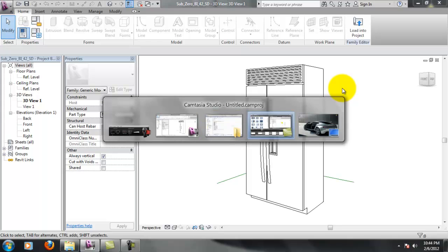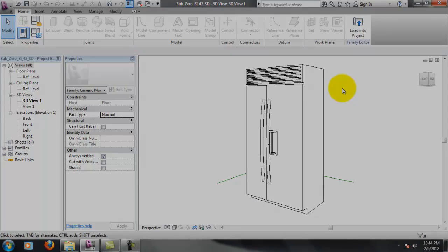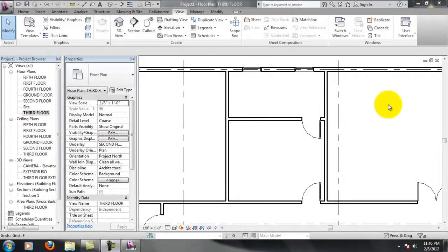So what I want to talk about now is actually the wall types in Revit and how we can modify those. Alright, so the families that we've been using up to this point have been editable. The walls cannot be editable because they're system families. And we know that system families are predefined. They're kind of like Autodesk's building blocks for Revit. So in order to actually create or modify walls, we only need to create types and modify the types.